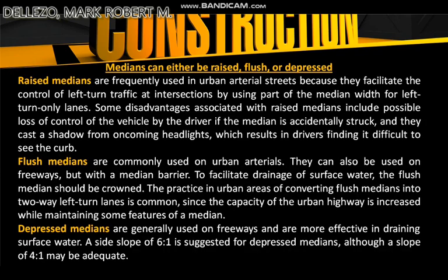So medians can either be raised, flush, or depressed. So raised medians are frequently used in urban arterial streets because they facilitate the control of left-turn traffic at intersections by using part of the median width for a left-turn-only lane.